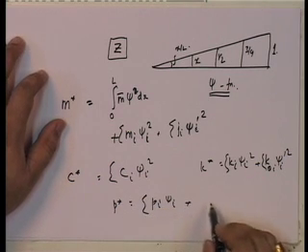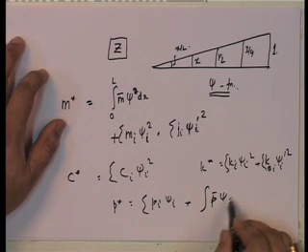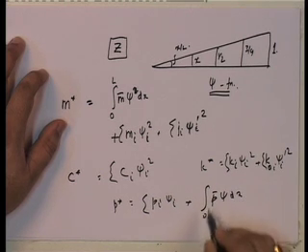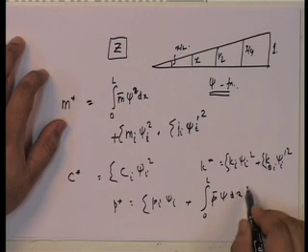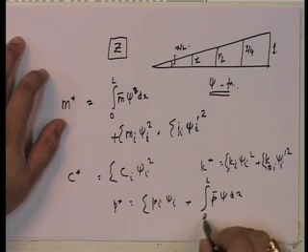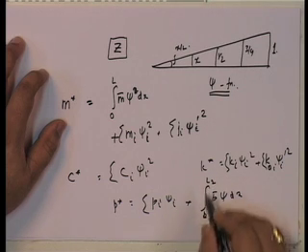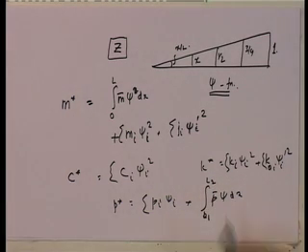And then if I have distributed loads, they basically become p star as the integral of the load times xi over the length. I mean over the length over which the load acts, not 0 to L; let me also say it can be L1 to L2, depending on the particular length over which the load acts. Okay. So, this is the beauty of this particular method.